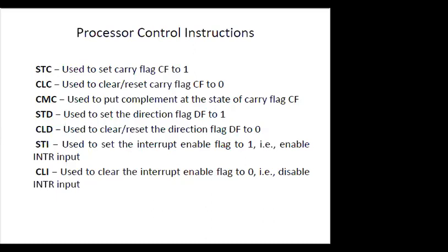If we are not changing data, maybe we are not manipulating data, but we are changing the status of the flags. So that part is known as the status manipulation. And by changing the status of the flag, we are changing much more in our process. As we can see, two instruction sets, the program execution transfer instruction set and the process control instruction set, broadly use the flag register to represent the status.